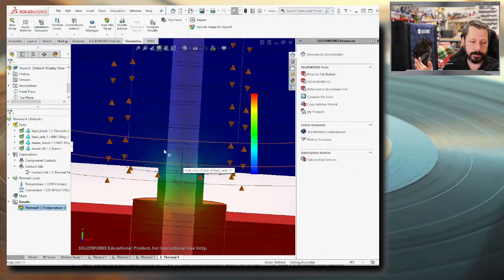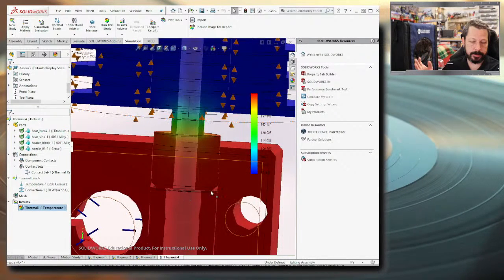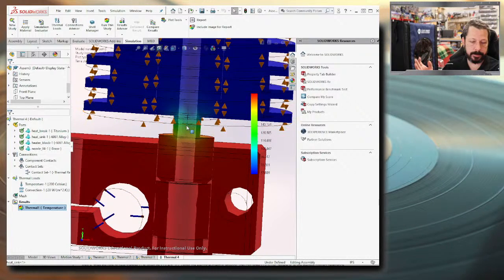And in some of your printers, this zone in a not all metal hot end has the Bowden tube right here. Well, actually it goes down further. It goes down to right here. Basically it sits against the nozzle. And so that could be a problem if you have that kind of temperature inside the Bowden tube.